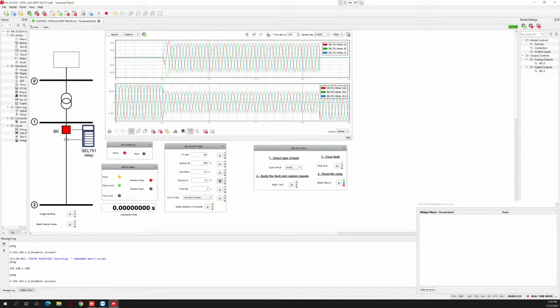And are you ready, Marta? No, the problem is solved. Right now we are receiving the current signal, 120 something over there. I am sending the settings of the inverse time overcurrent. In this case, you can see over here we are using the US very inverse curve.